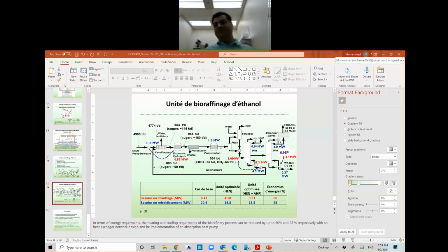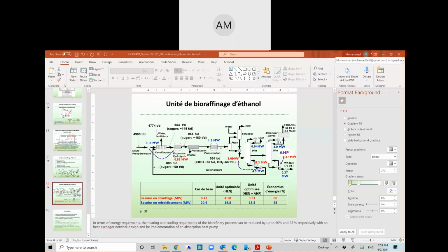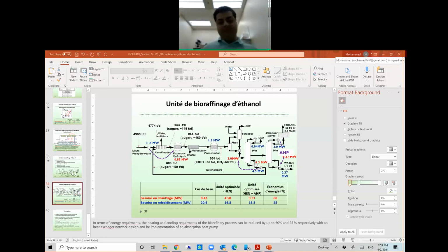Yeah, and if I could remember, sometimes you can break the pinch. For example, sometimes we want to modify an available process. We have some bottlenecks, and we can cross the pinch point to insert a new heat exchanger. But the key point is, when we talk about pinch point, our focus is on process-to-process heat exchangers.